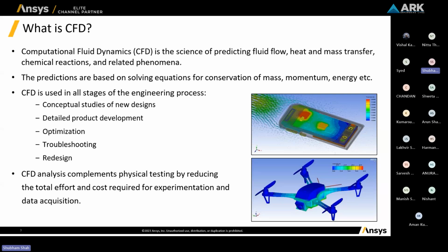So what is CFD? CFD stands for computational fluid dynamics. It is the science of predicting fluid flow, heat and mass transfer, chemical reactions, and other related phenomena. These predictions are based on numerical equations known as the conservation of mass, momentum, and energy equations. Now, at which engineering stage can CFD, or let's say Icepack, be used?